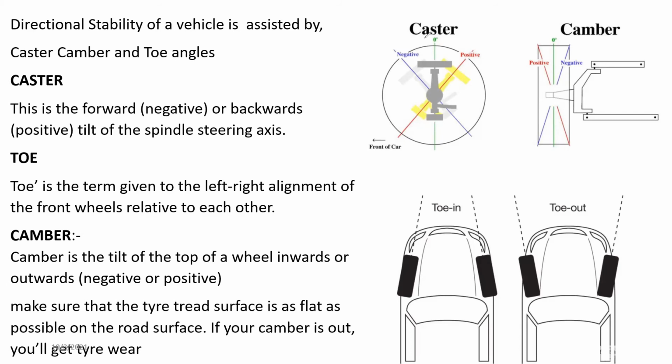That's what the camber is used for. Next we move to toe in and toe out, which make sure that the vehicle always travels in a straight line.